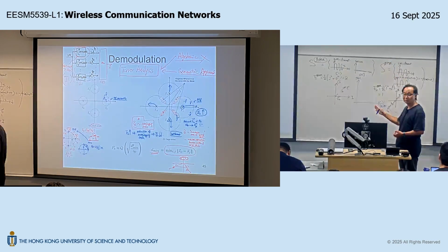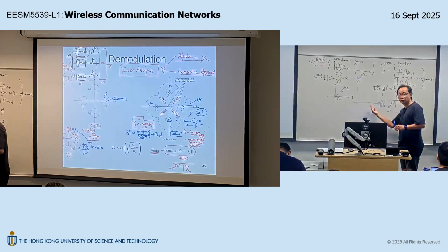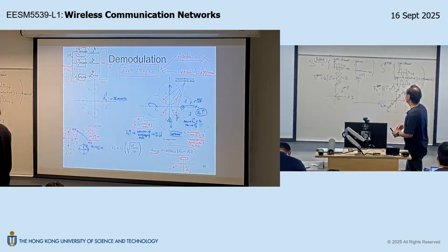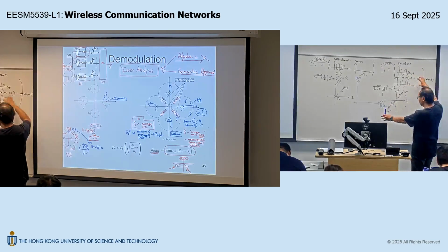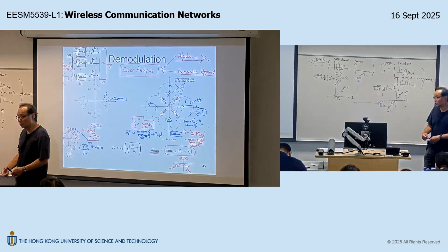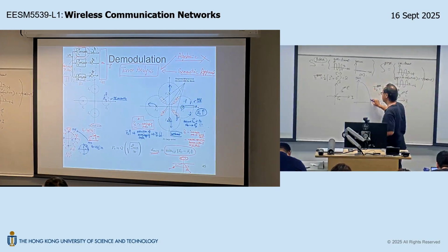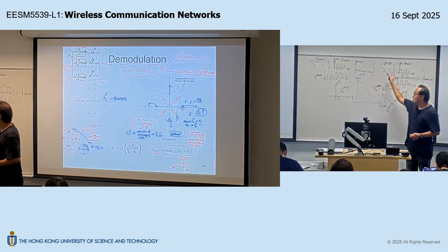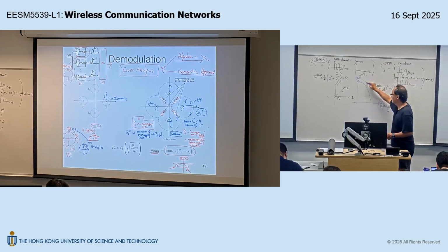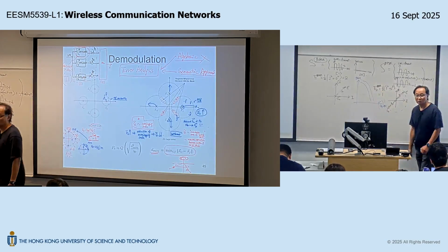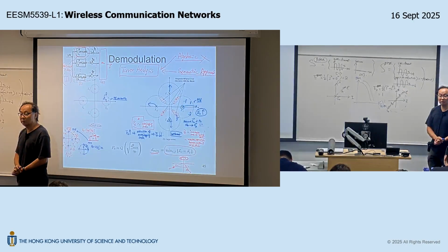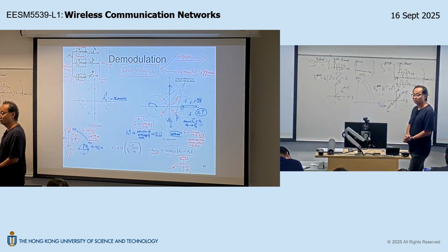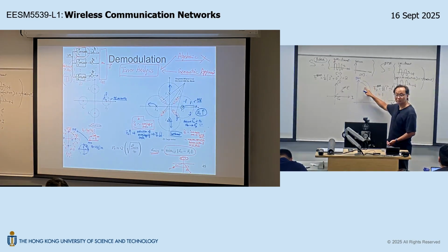Decreasing. Why? Because as we increase the symbol energy, geometrically, we are moving this point away, right? So moving this point away can only reduce the overlapping area. So we expect the curve to be like this. Is that okay? Now we have 2 designs, so we have 2 curves. One would be BASK, one is BPSK. Which one is BPSK? This one or this one?